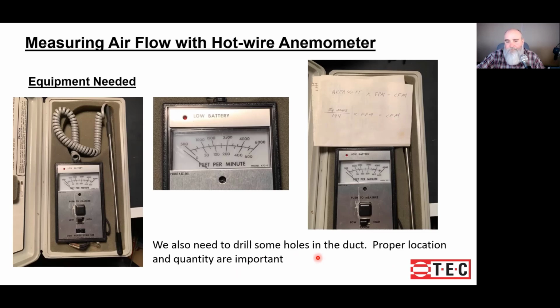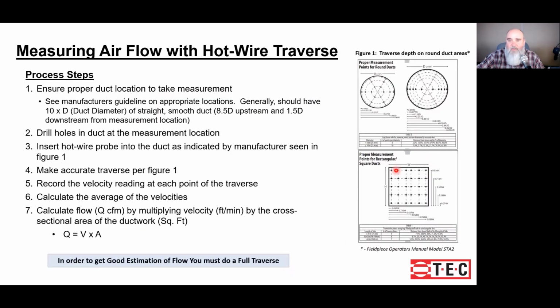Drill some holes in the duct. The proper location and the quantity are important. What am I referencing there? I'm referencing figure 1 over here to our right. Figure 1 is an example of what is involved with doing a formal traverse.